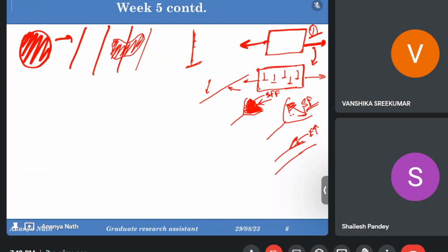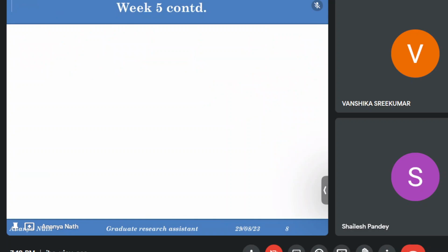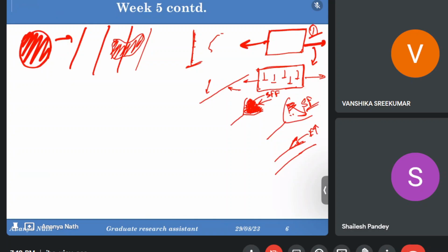If we are talking about the dimension of the pile up, it means there are a lot of dislocations piled up at a particular place. I have demonstrated the picture now. It's a black portion like this, so there are, you can say, thousands, millions of dislocations over there. This is why it looks like a black portion under the microscope. Otherwise, you can imagine a dislocation is made up of only a few atoms. You really can't see a few atoms under a microscope. Is it okay? Yes, ma'am.